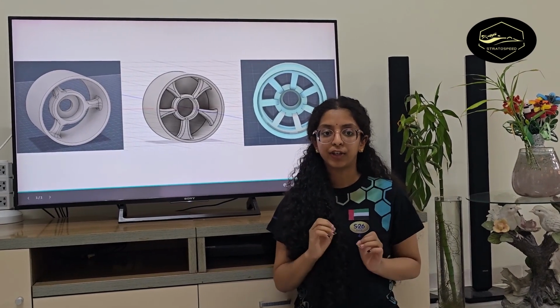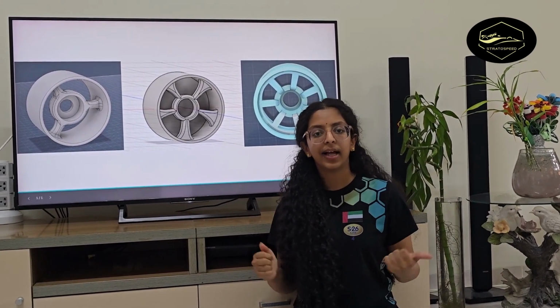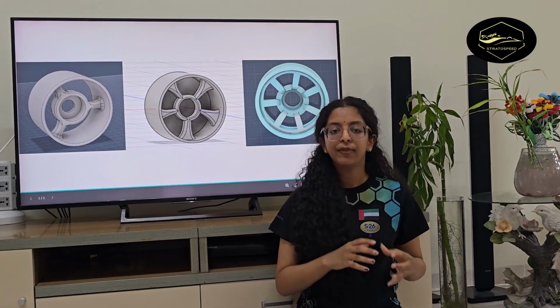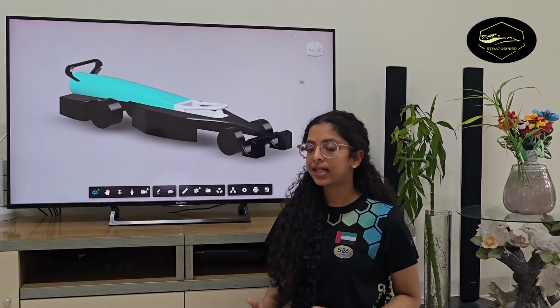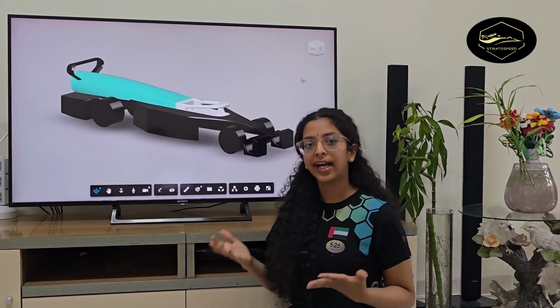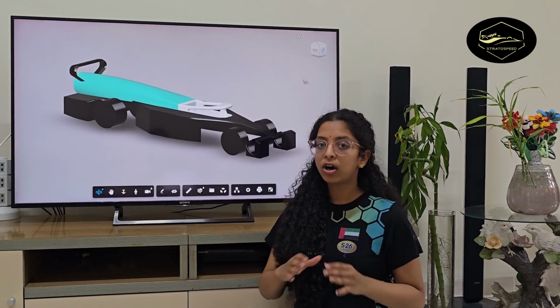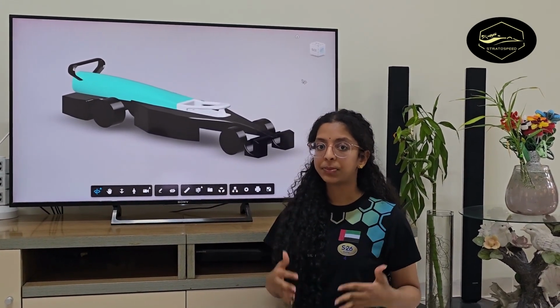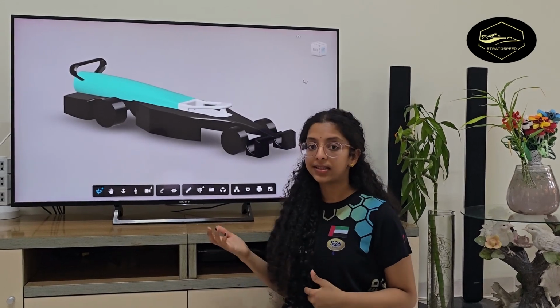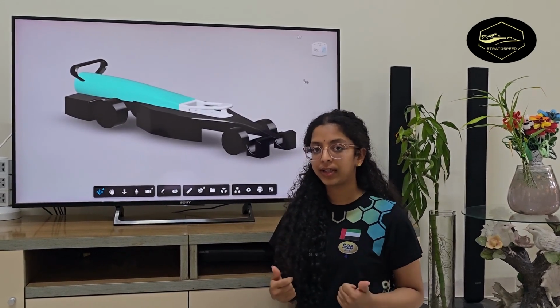Ceramic has a very low friction coefficient, handles heat well, and the small size keeps friction centralized, which all adds up to less energy wasted. Prototype A started as a hand sketch, then became an early CAD model. From a design standpoint, I could already see potential problems. The nose was too wide, and the surface transitions between panels were quite sharp. My concern was that the air would struggle to follow the body cleanly. And the CFD confirmed it was the worst result out of the three.